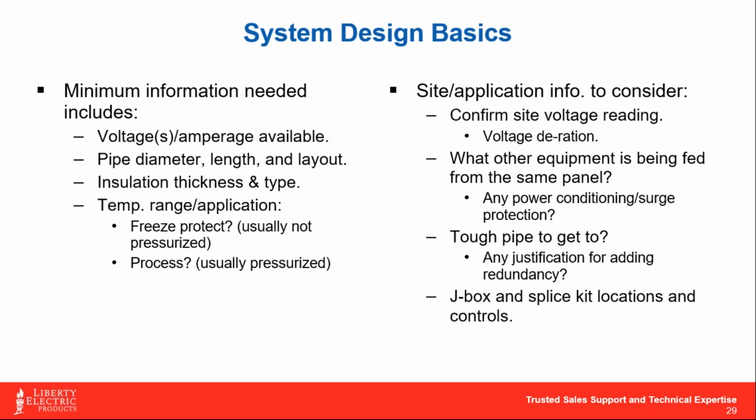Some other things that we would strongly recommend is confirm your voltage site reading. I mean, we can all read that it's 208 coming out of this panel or it's 277 coming out of this panel, but what do we truly have there? Because especially when we're talking about 208 volt, we've got that voltage derating to consider.